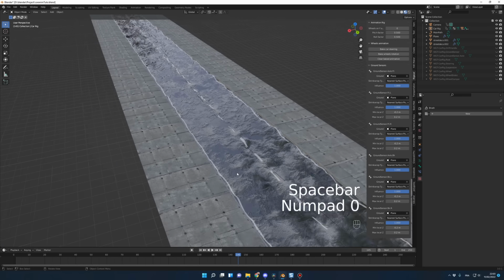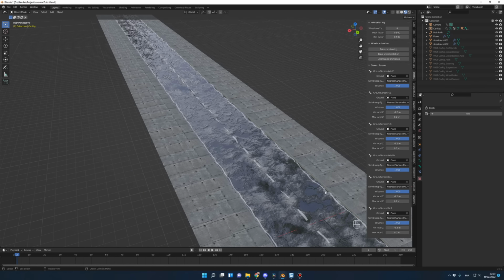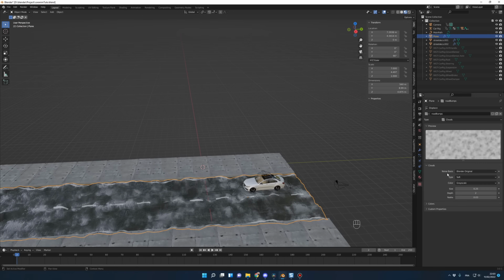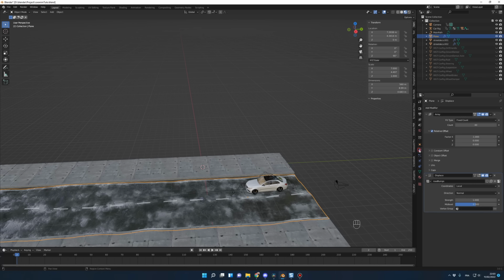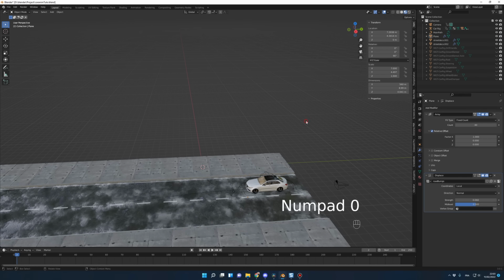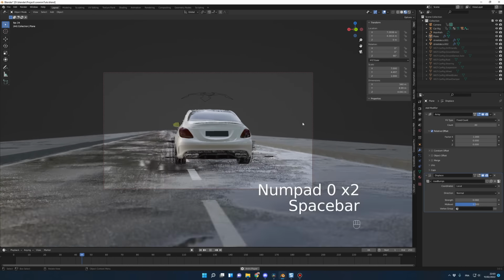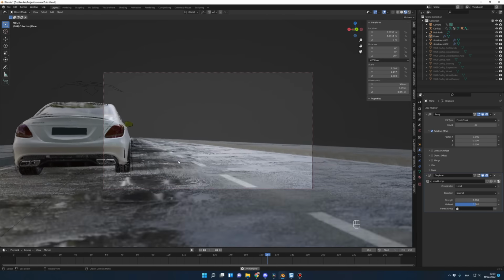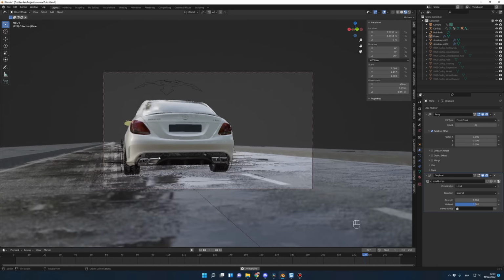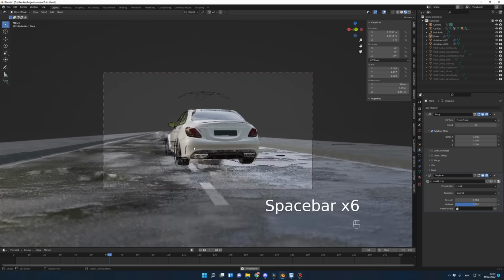Okay, now obviously it's a little bit too much. So let's fix the texture. Size 1.3 and depth 3. And then you go back in the modifier properties. And for the strength, I will lower it to 0.06. Okay, let's see again now. And now you see our car is moving like there were little bumps on the road. So it's adding again to the realism of the animation.